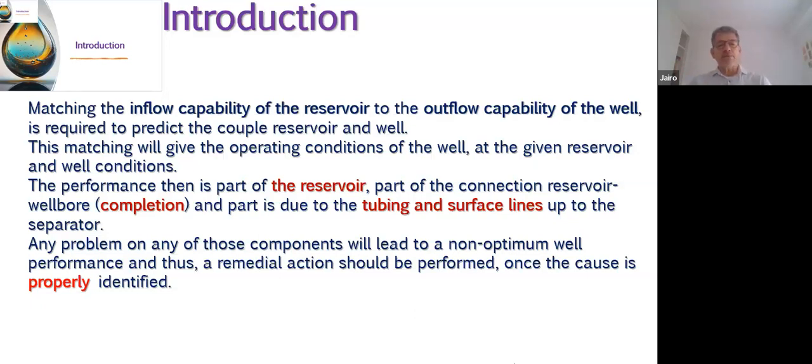The performance is part of the reservoir and part of the connection between reservoir and wellbore, which is completion. This is the definition of completion. That's another common misunderstanding from industry: you hear upper completion, lower completion. The technical definition of completion is the connection of the wellbore to a reservoir, how you connect the reservoir to the wellbore in order to get the optimum performance of that well.